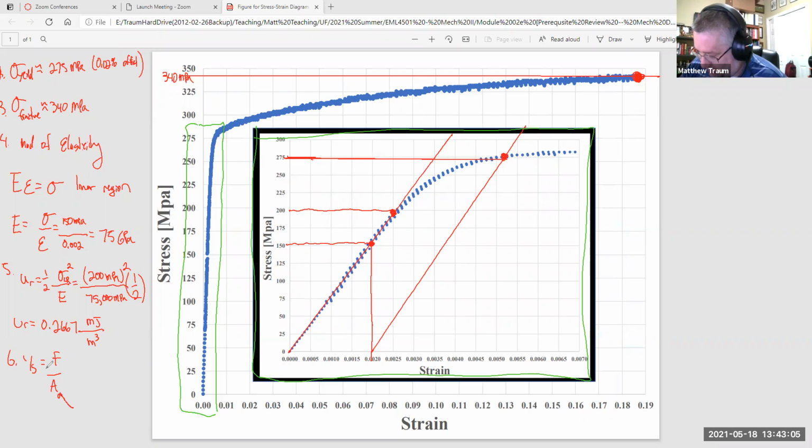This is the area that I'm given, 50 millimeters. And this force is the force that I can apply to the sample before it starts to yield. So again, the maximum axial load that can be sustained without any permanent deformation, permanent meaning plastic deformation. So I'm just going to reorganize this, and I'm going to say this is the yield strength multiplied by this area that I have is equal to whatever force it can sustain.